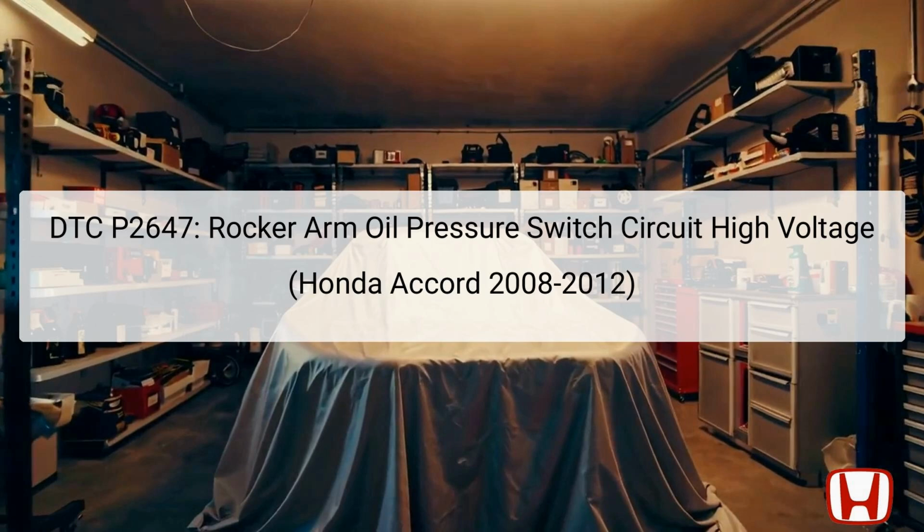The rocker arm oil pressure switch plays a critical role in ensuring that oil pressure levels are maintained, which is vital for optimal engine performance and efficiency. If oil pressure is too low or high, it can lead to engine misfires, decreased performance, or even engine damage. In order to effectively troubleshoot this DTC, a structured approach must be taken, starting with ensuring the basic engine oil level is appropriate before moving on to more specific testing protocols.